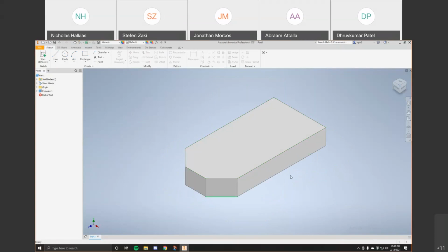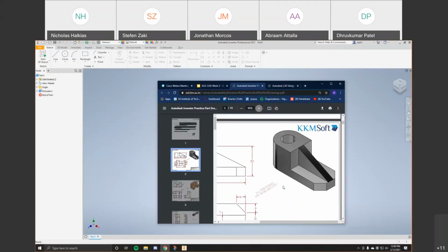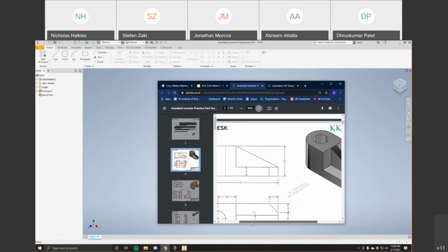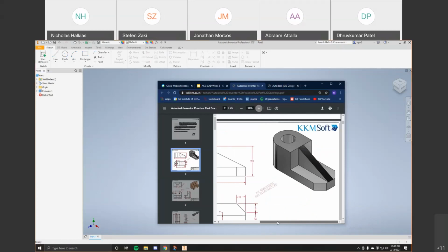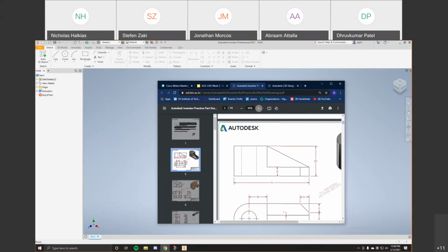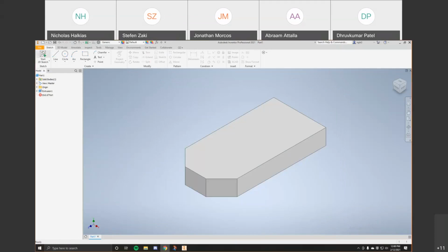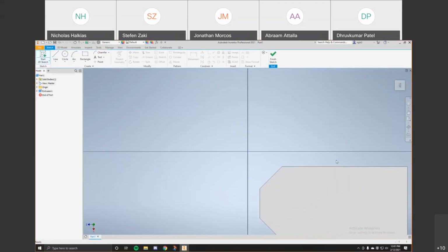So next thing we want to create, looking at this, would probably just be this upper part. Not the diagonal part yet, but this upper part. That's the next easiest thing to do. So based on that, we're going to create another 2D sketch. When we go back to sketch, we want to start a 2D sketch. Notice how no 3D coordinate grid shows up. It only lets me select certain faces and planes on the object. So we're just going to click on this top part because we want to draw on the top. And now that's our new plane.